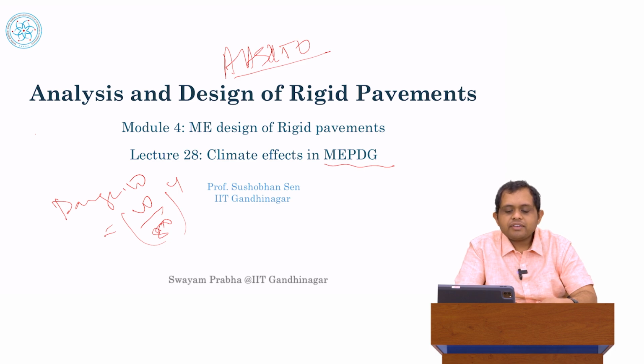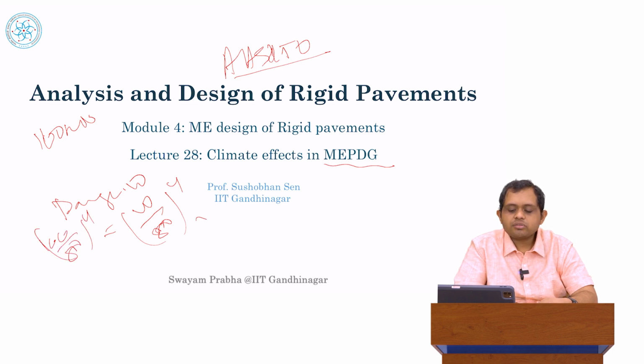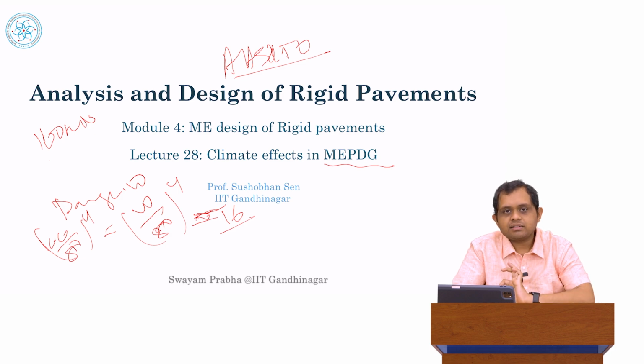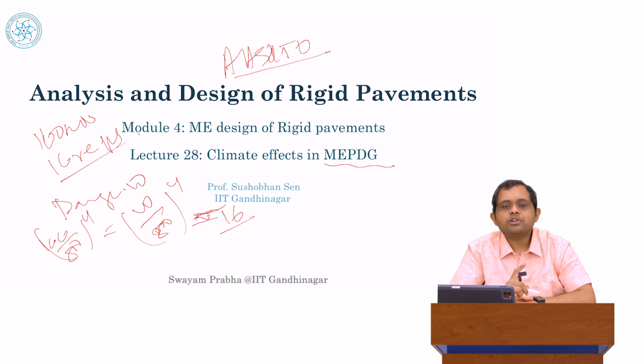So for example, if we have a 160 kilonewton axle, that's double of 80 kilonewton, its damage is going to be (160/80)^4, that is exactly 16. So what we say is that one repetition of a 160 kilonewton axle is equal to 16 repetitions of an 80 kilonewton axle, and an 80 kilonewton axle we call a standard axle. In this way, we can look at all the axles that we have on the pavement converted into standard axles. This is the empirical approach.